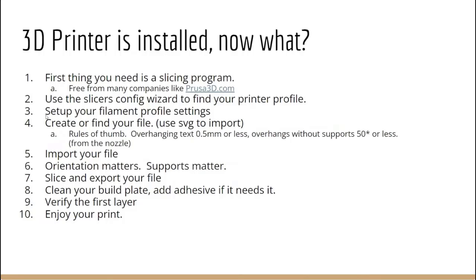So we'll go over the configuration wizard, and then after that we'll get into setting up filament profiles. There are stock profiles, but in my experience, not every PLA loves the same temperatures, not every PETG, and these are the filament plastic types, that's what those letters represent. And so sometimes you have to dial it in. You might have two different brands of filament and one print's fine, but then you print with a different brand and it starts stringing and it leaves plastic hairs or wisps all over your print. And there are things you can do about it. So we'll talk a little bit about that.